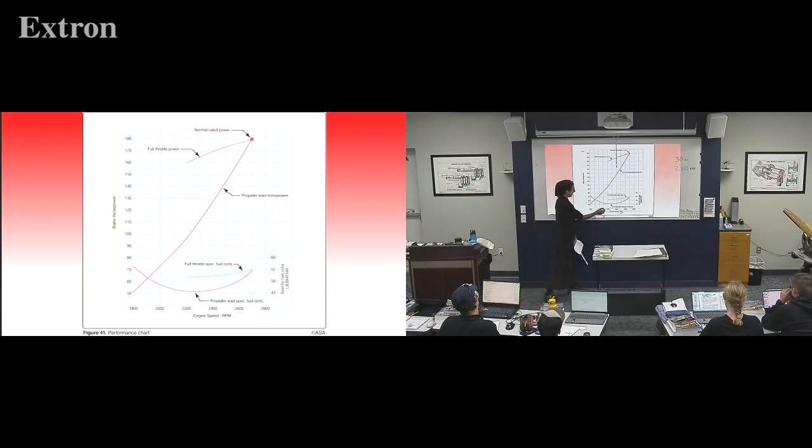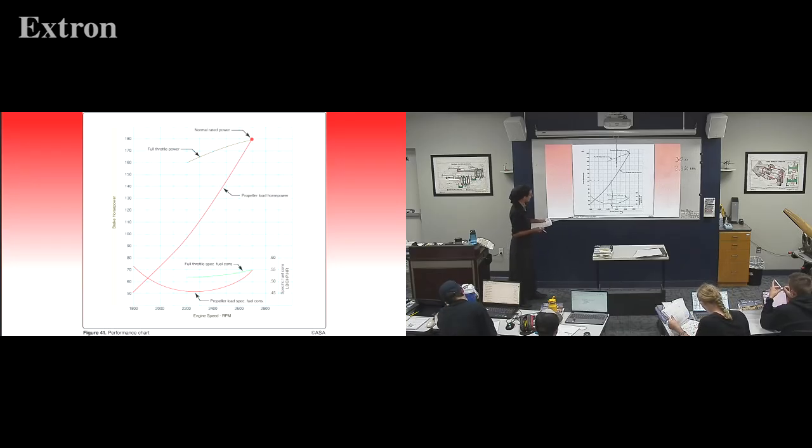So at 2,300, we come up here till we hit the red line. Come over, we're just a little bit above this blue line. And again, yours are going to have more specific delineations between there. But we're right about 110. So we're going to take our number 110 and save that for brake horsepower.